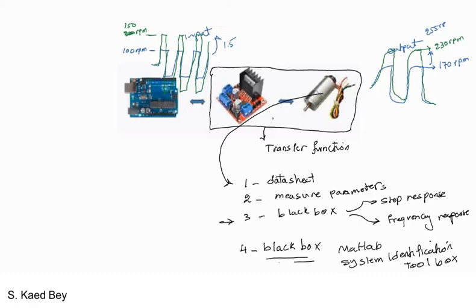However, in reality, you should have many more inputs in order to capture all the dynamics of your system or plant. For example, you could have multiple sawtooth input signals with variable periods, or sinusoids with a variety of frequencies, or perhaps varying square waves where you can capture more information about your system, and so on.